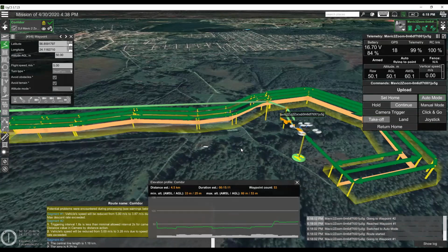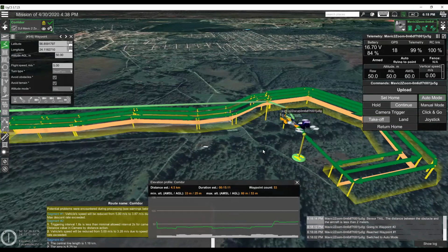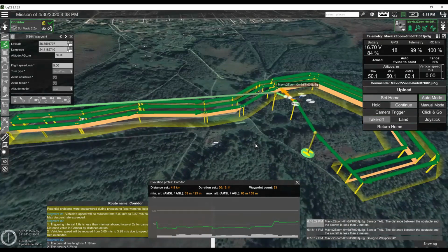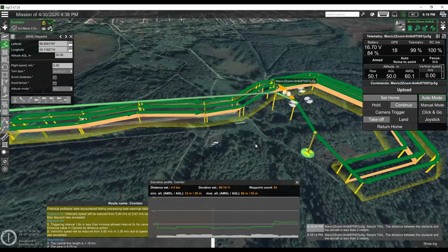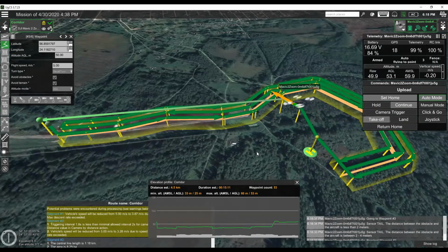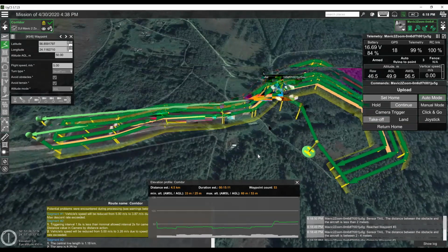If there's a situation that there is no signal where the drone has stopped, well, then the only option will be to go closer and return the drone home manually. So that's the reason why it's important to research the area of the flight before the actual flight and understand where the drone will finish the flight if it's not returning completely home. So this will be all for the manual creation.